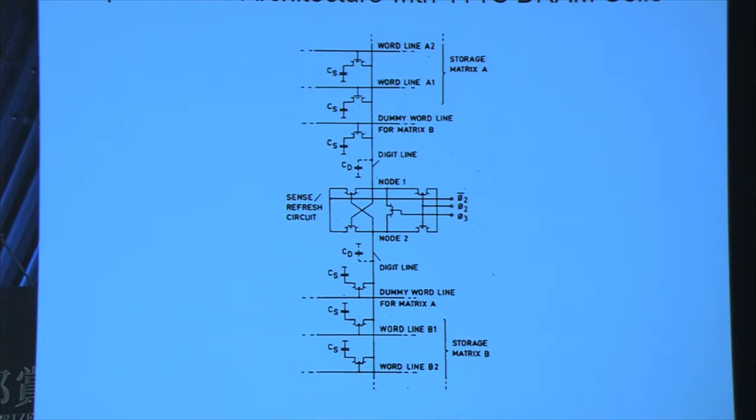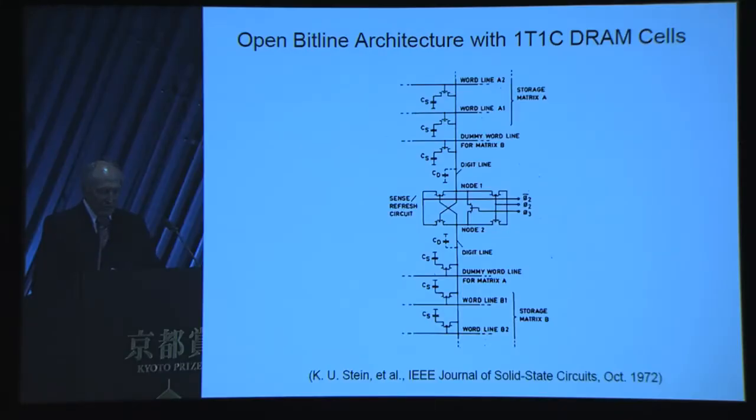Then, raising the voltage on any word line in this array turns on the transistor in the associated memory cell, causing the capacitor connected to it to charge or discharge a bit line, so the latch is unbalanced in a direction corresponding to the voltage stored in the memory cell. The beautiful thing about the latch, when it is activated, is that the small signal unbalance is amplified up to full digital levels.